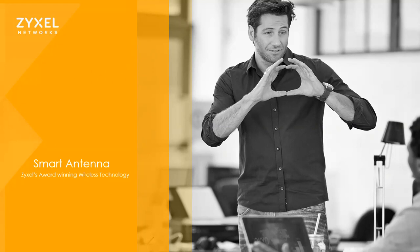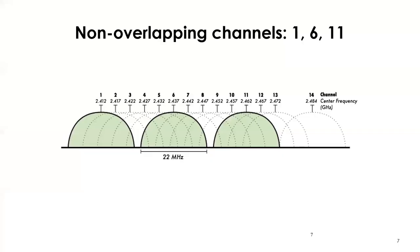Before we get too in-depth on smart antenna, I want to talk briefly about co-channel interference. When it comes to using wireless devices, access points, whatever, we've got certain amounts of spectrum that are opened up to us that can be used, right? Most APs these days will have 2 radios. One radio works on 2.4 gigahertz. The other radio works on 5 gigahertz. Those are blocks of spectrum that are available to us. The problem we run into when using that spectrum is that basically only one device is able to transmit at a time. If you've got multiple devices transmitting at the same time, you run into interference.